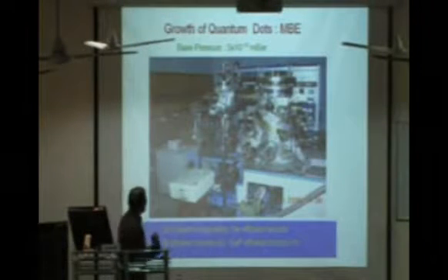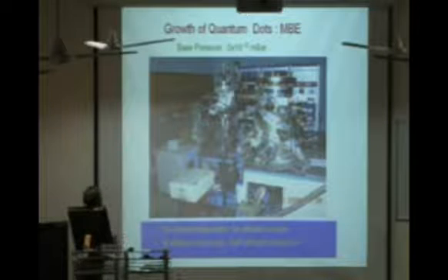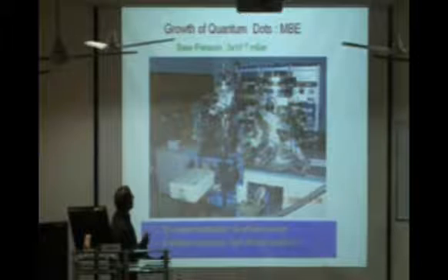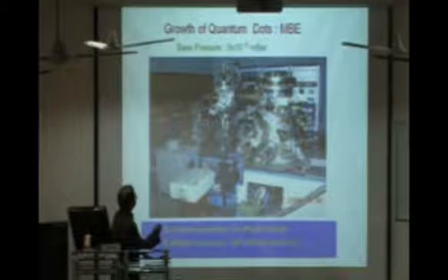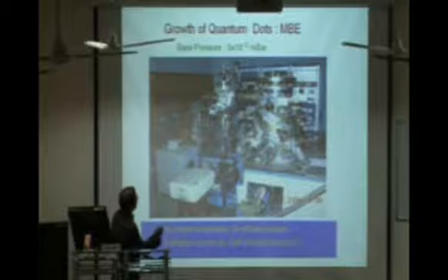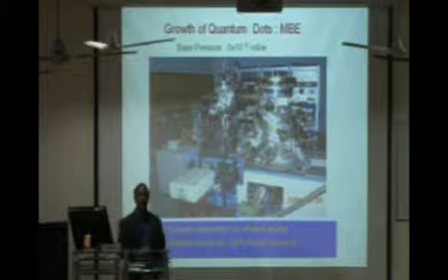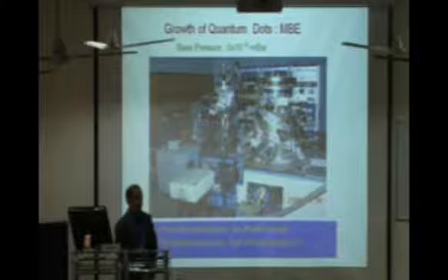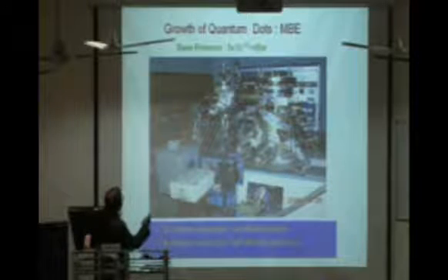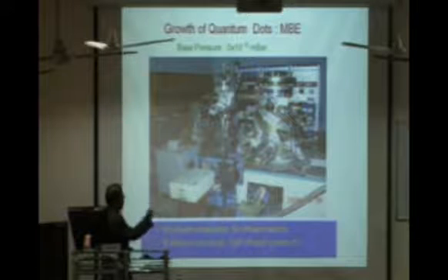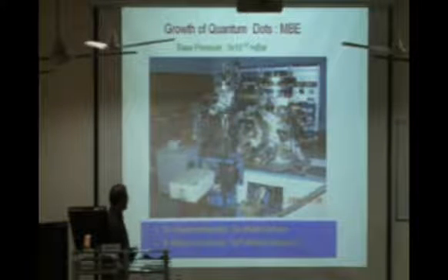Those are more stable. In fact, the system that we use in our Kharagpur lab is called molecular beam epitaxy. This is a very old system we have had about 20 years back. This is where we put the semiconductor materials for the growth, like silicon and germanium, in different sources, and all this takes place at a very high vacuum, 5 into 10 to the minus 10 torr or millibar is the typical pressure. And here we put our sample and then load the sample from here to here without breaking the vacuum, and then we grow the materials.